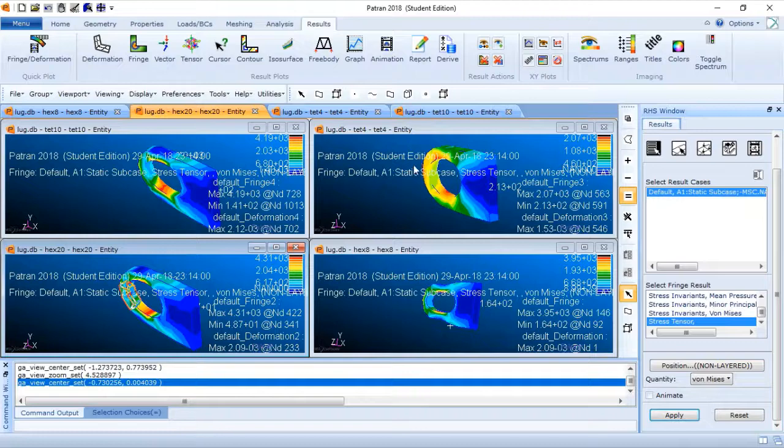And also another thing to note is, as you remember, in the TET mesh, we didn't have to break the model a lot to mesh it with TET. So the TET mesh is a very convenient approach because, as I was saying, it is not necessary to break up the solid into many parts like for the hex we had to do it.